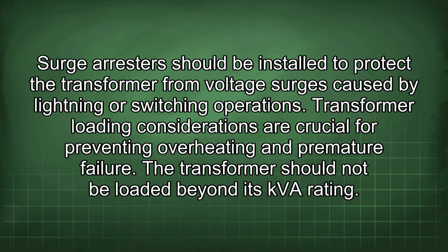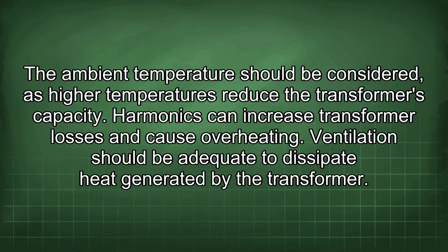Transformer loading considerations are crucial for preventing overheating and premature failure. The transformer should not be loaded beyond its KVA rating. The ambient temperature should be considered, as higher temperatures reduce the transformer's capacity. Harmonics can increase transformer losses and cause overheating. Ventilation should be adequate to dissipate heat generated by the transformer.